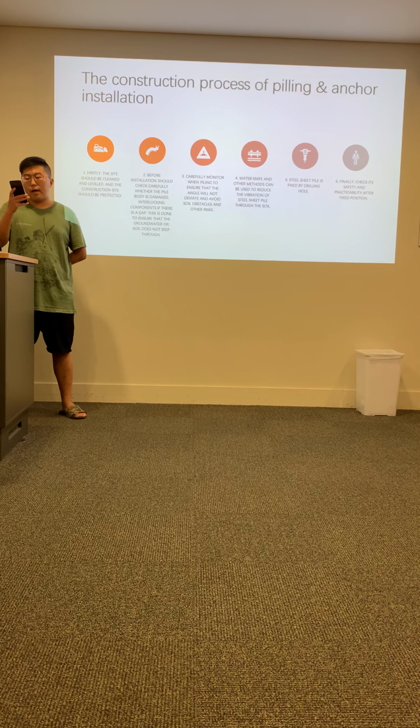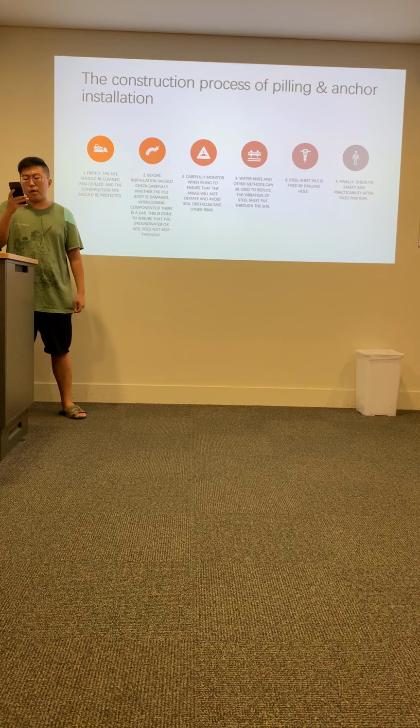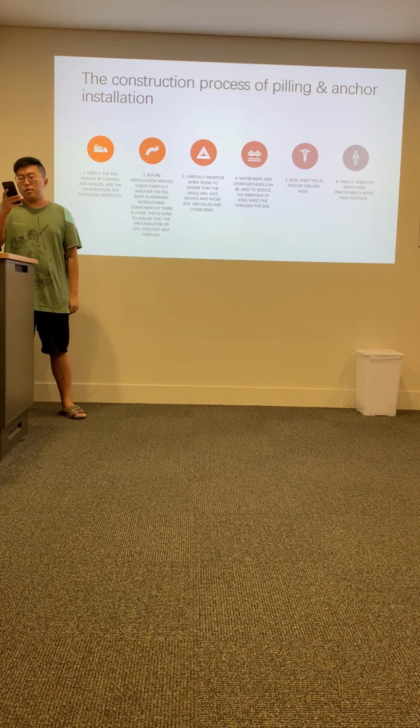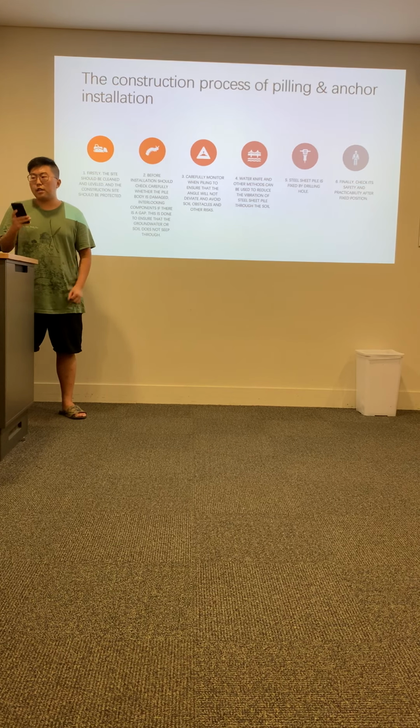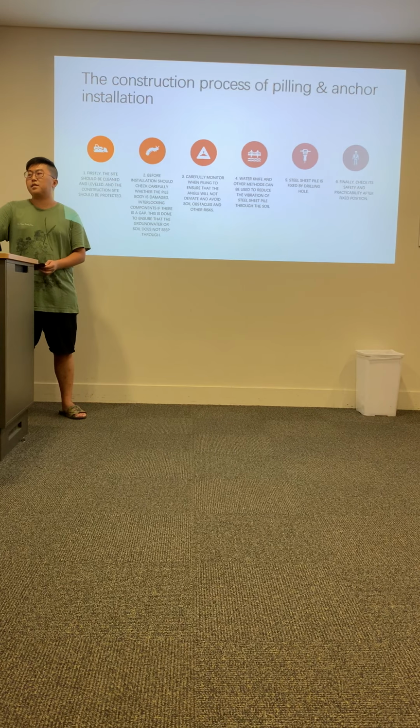Drill the hole with a high strength thread bar or continuous flange angle, and then perform high strength grouting on the hole. Upon completion, work outside with soil nails and walers to complete the steel sheet pile fixation. Finally, check its safety and stability after it is fixed in position.